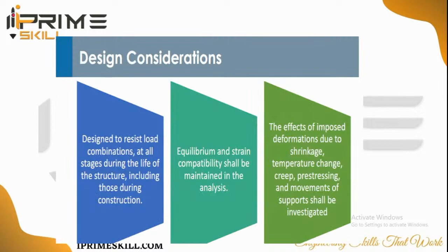What are the designs to be considered? Okay, when you design a bridge during the lifetime of the structure, to design to resist all load combinations, there is a code which you have to refer to, where all load combinations should be taken into account. Equilibrium and strain should also be maintained, and temperature change, pre-stressing, movements, supports, all these things should be investigated properly to have a proper design.